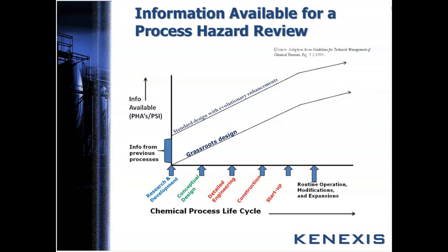There are essentially two methods that are used to identify areas where safety instrumented functions are required to reduce the risk in the process. The first is through process experience. Most processes are not new, they rarely are started from a blank slate, okay? Process design is, in many cases, based on proven technology that's been used over the years. And these are often process design templates from licensors that have safety instrumented functions already identified, and key safeguards and hazards already identified.